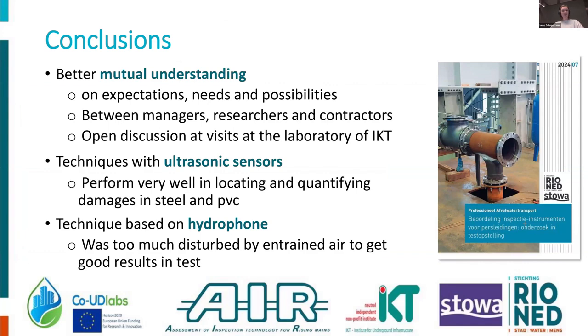So to conclude some of these experiments, I think very valuable information is to understand that the techniques are there, and they can do quite some good inspections, especially the techniques with the ultrasonic sensors. They perform very well in locating and quantifying damages in both steel and PVC pipes.